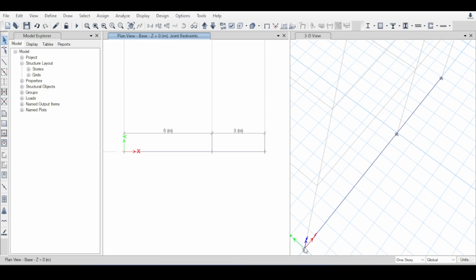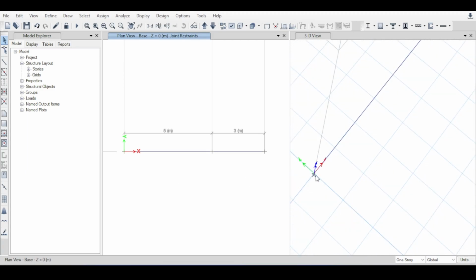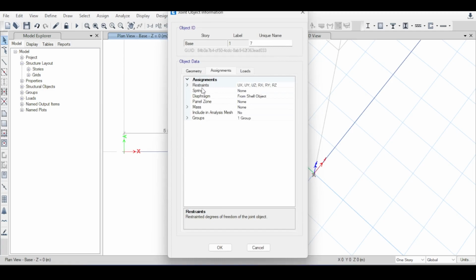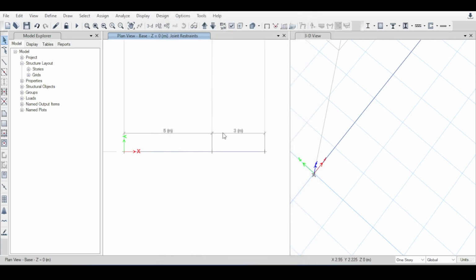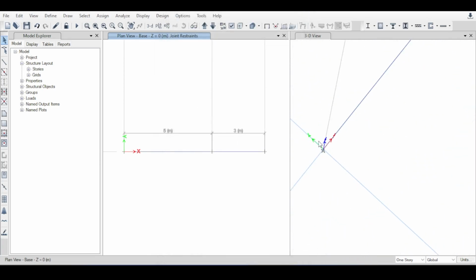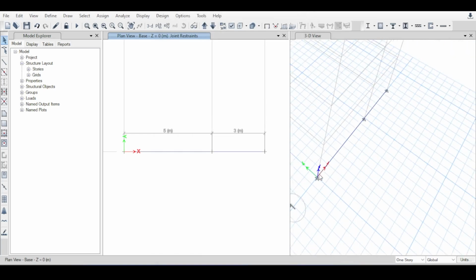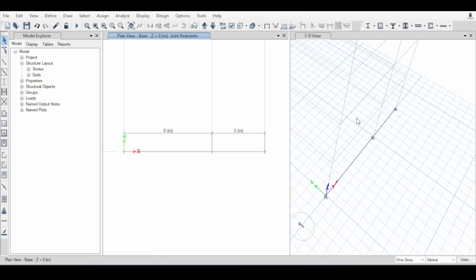And it seems it did not refresh here. Let me check very quickly. It seems it did not refresh. So how do I check? Well, I stand on the grid, right click, and check. Restraint is UX, UY, UZ, RX, RY, RZ, exactly as I want. And just use another software to see something here, but it seems that this little star is just a symbol that is used for all types of restraint. Maybe I'm wrong, maybe it needs time to refresh, but I will accept that.